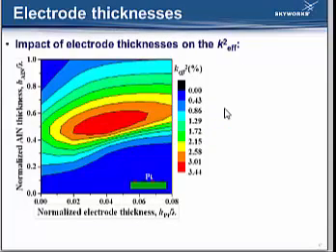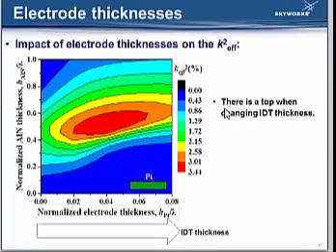Here, this contour plot shows the effective coupling versus IDT thickness for the single IDT configuration, and the material is platinum. The first observation is that the effective coupling reaches the maximal value at a certain point in the middle. This is because when the IDT thickness is increased, the reflection of the IDT increases, which enhances the electromechanical transduction. But when the electrode becomes too thick, the non-piezo layer deviates the resonance wave from the piezo layer and reduces the piezo transduction.